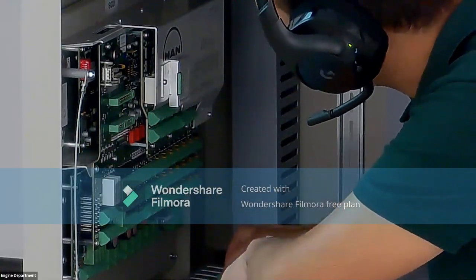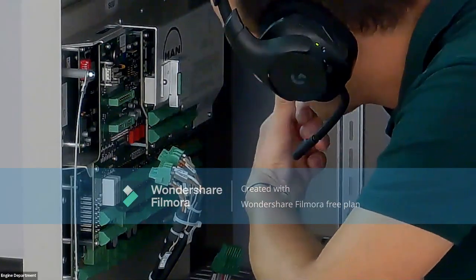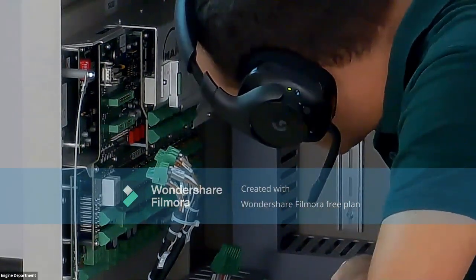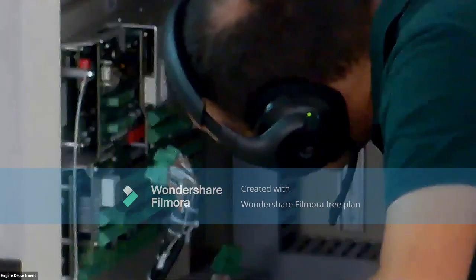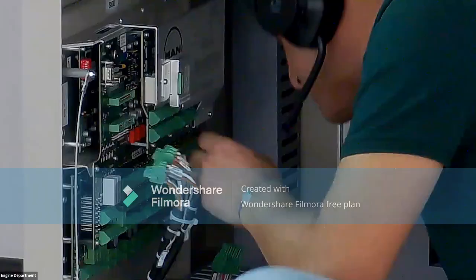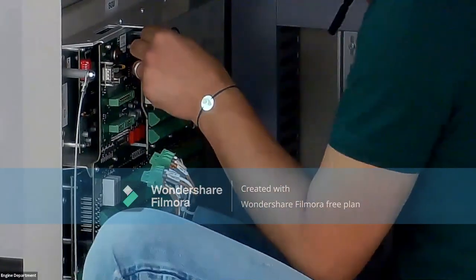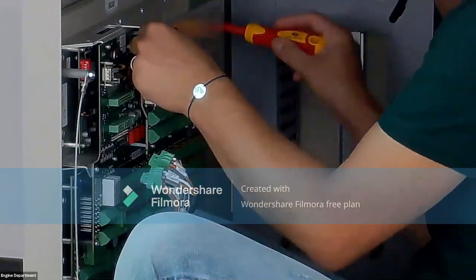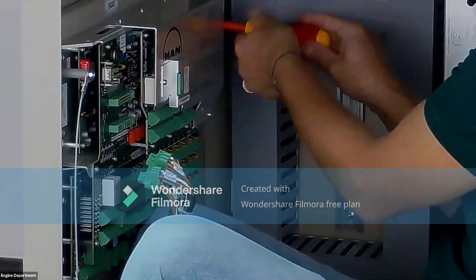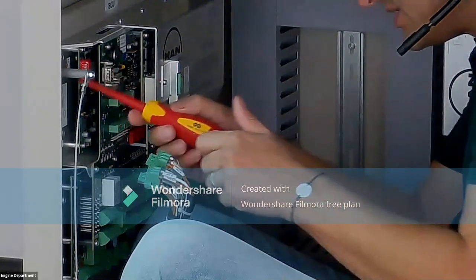Okay, so you'll see we don't have any connection left on the MPC. Next step, remove the MPC from its position. On each side of the MPC we have 4 screws, 8 in total, that need to be removed. I will use this position because it's easier for me to remove from here. For all other positions it will be much more difficult to replace.